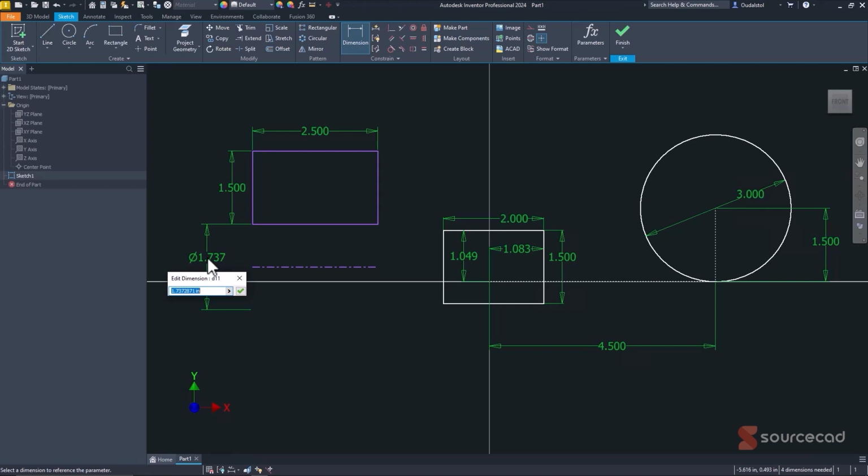And so with that, I'm going to make some a little bit more functional sketches at the time, but I just wanted to show you this so that you might want to use the different line types for what you're going to do. Basically these are the 3 ones. You can make this a center line, and you can make it a construction line as well. It just makes it thinner. And you can turn them both back off, and it doesn't change this, or turn it back on.